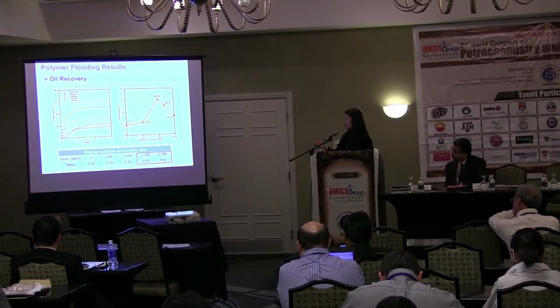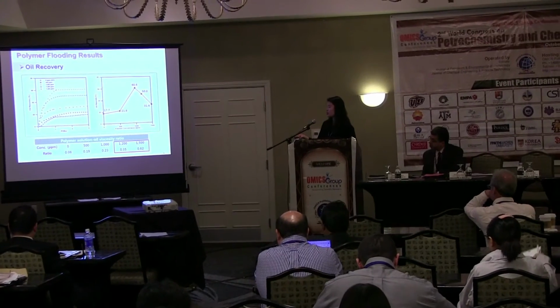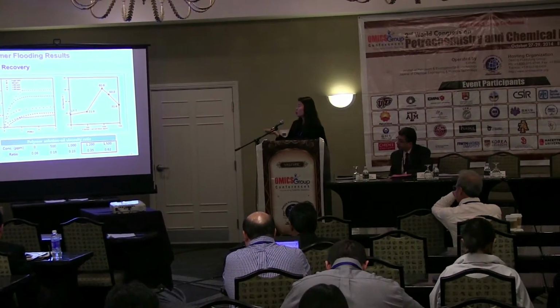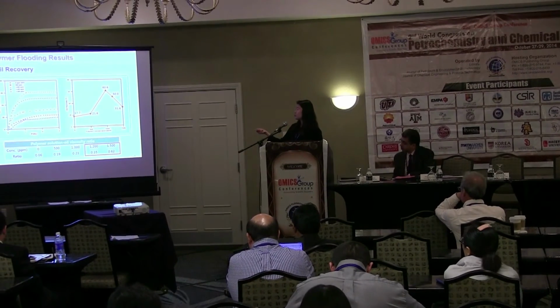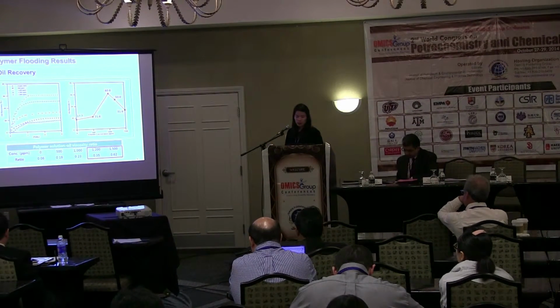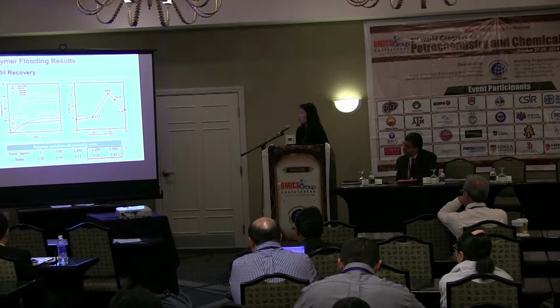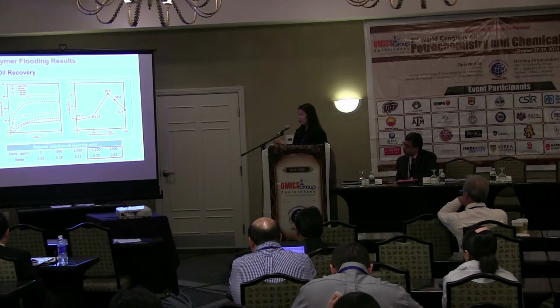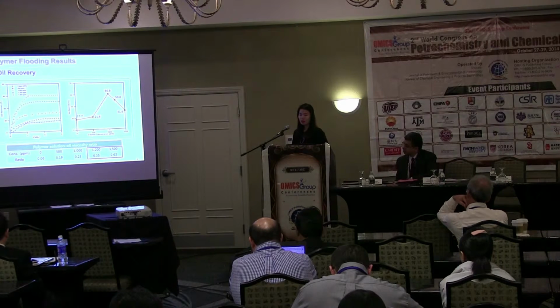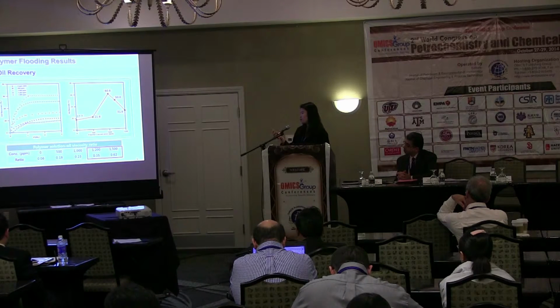But on the other hand, in the case of 1,200 and 1,500 ppm injection, the oil recovery rather decreased to 50% and 31.6%, even though the viscosity ratio further increased to 0.62. We thought this may be attributed to the low permeability of this system, and the polymer retention that happened as adsorption and entrapment during the polymer flooding. So these results will be verified by the following analysis.